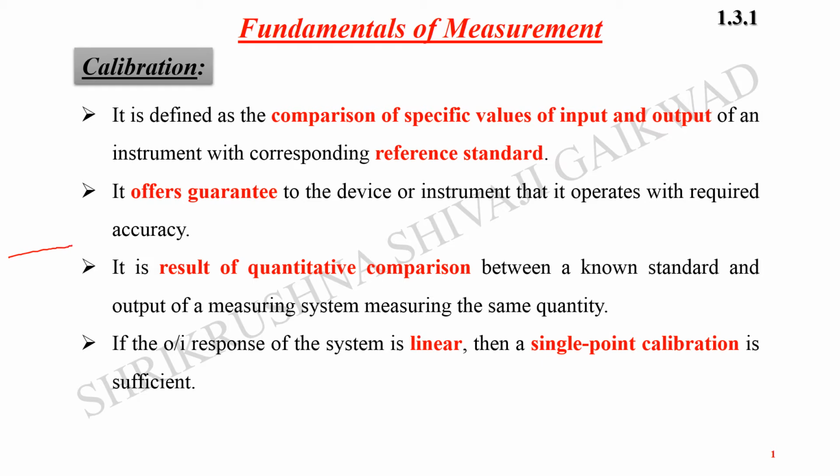If the output and the input response of the system is linear, then single point calibration is sufficient.